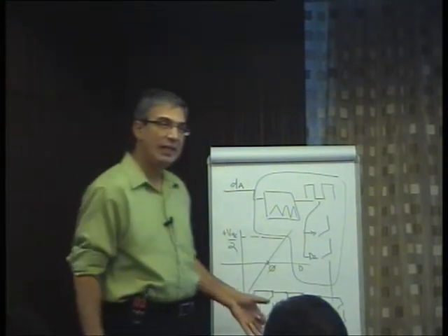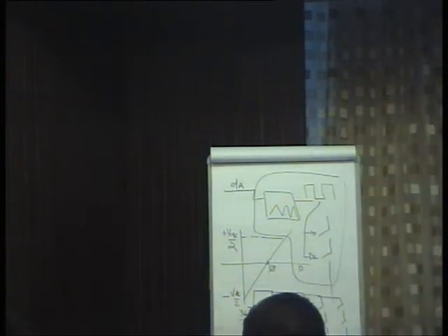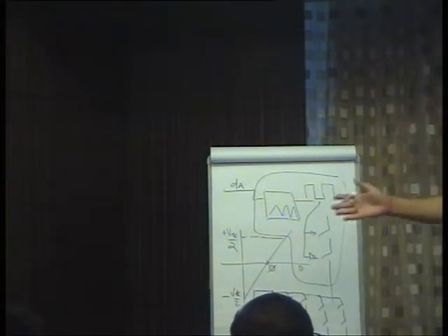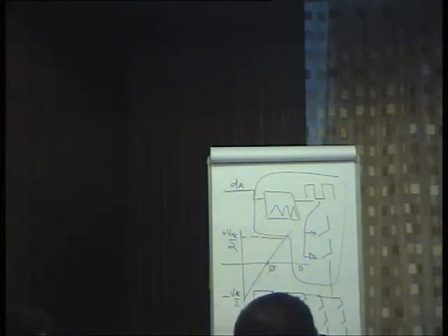So you take the inverter and replace it with this block so that you can get much bigger data on the motor side. To be able to do this is great because otherwise this allows you to get the torque speed curve, which is very critical information. Otherwise you don't have the torque speed curve. There's no way for you to figure it out. So if you can feed in the correct model of the motor, which I will show you how we have done, then you have something useful.